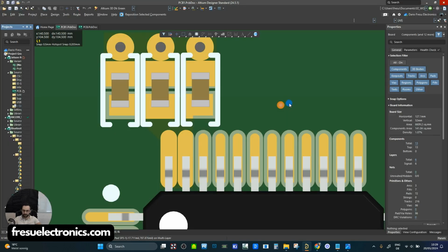So the best way to design this power delivery network is to select the package and the capacitance value, and then to multiply these so that we have the effect of a parallel capacitance. In this way, we also reduce the inductance.